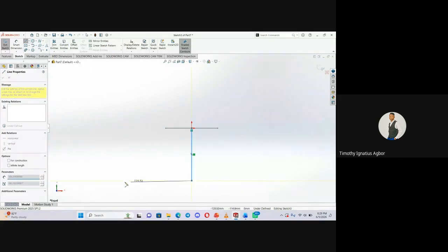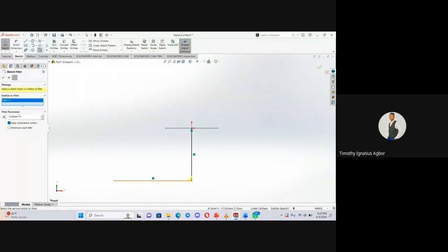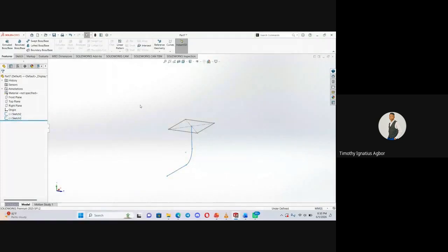go down and click. It can be a curved line or a straight line, depending on what you are trying to achieve. So I can curve here. Let me curve here. Let's say, let me give it 40 mm. So this is the profile for my chimney. So this is called the profile, and this is called the path that my chimney is going to follow. So I come here and I go to sweep.